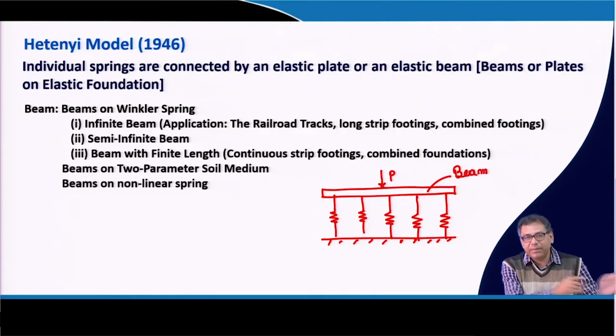So, now in the previous model the interaction between the foundation and soil was not considered, it is only the soil. But now in this case, if the foundation is idealized with a beam or plate and the soil is idealized with these mechanical elements, that means either spring or spring dashpot, now there is an interaction between these plate elements or beam elements with these mechanical elements. Okay, now here also these connectivity issues can be solved, and now the settlement will not be confined within the loaded region.